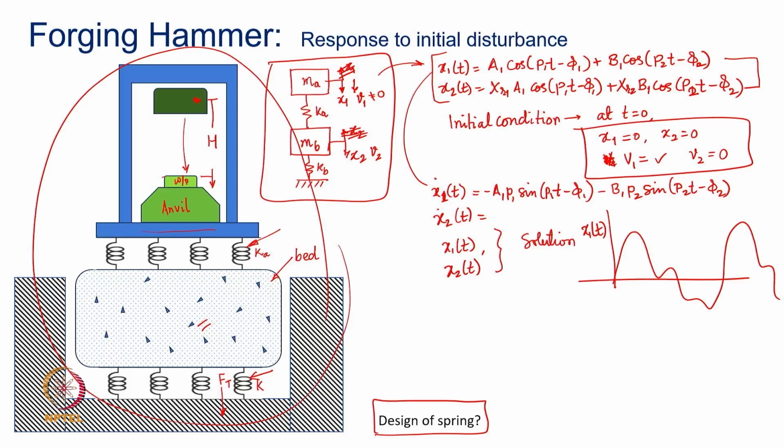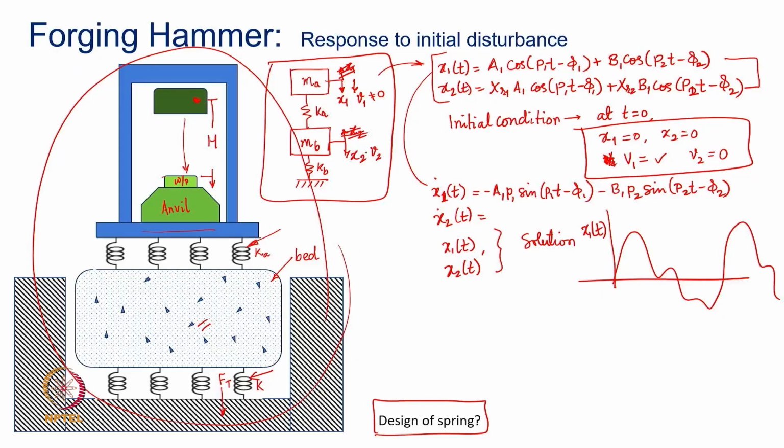Now, many times based on your strength of material or based on your machine element design, you fix the spring dimensions based on a certain value of load that it takes or a certain value of spring rate that it has. But that is the reason why this vibration analysis or vibration theory is very important for you to understand. Now you are not talking about only the load. Why? Because you can imagine that both of these masses are moving independently,